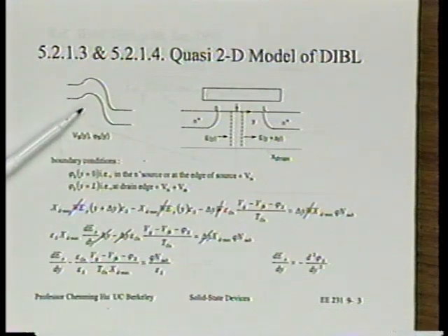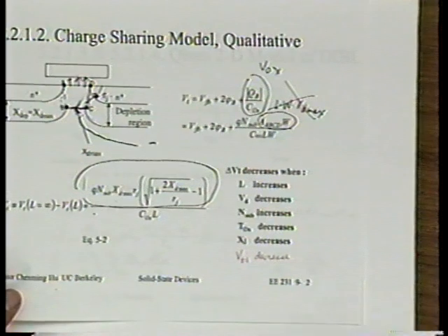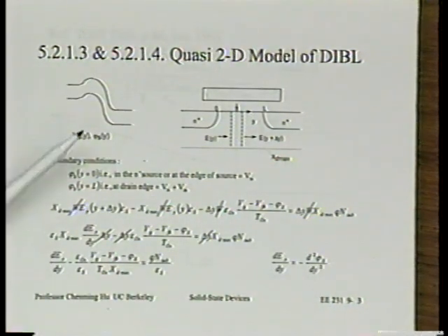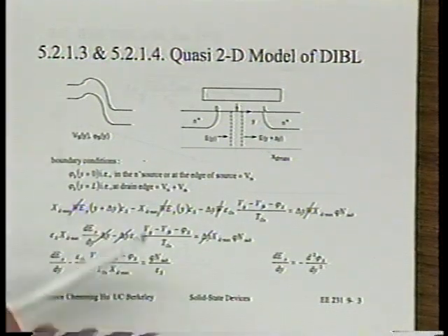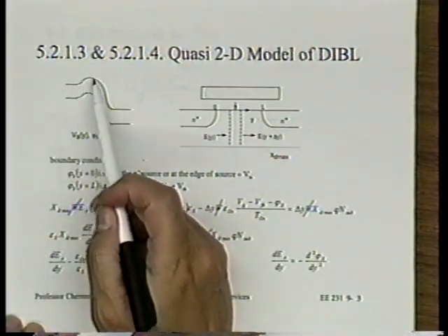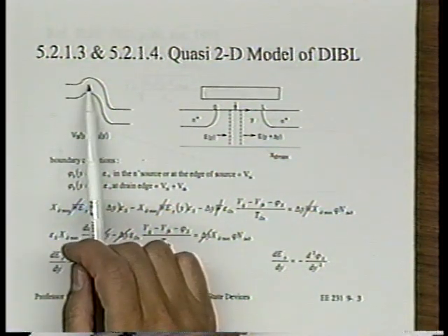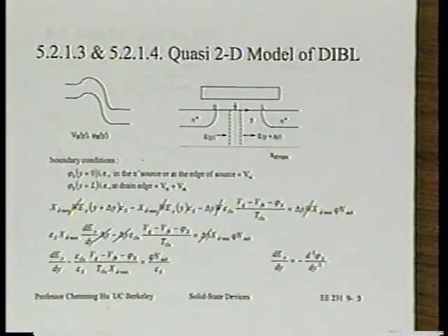So I really think that just by having this picture in mind, you can already answer the earlier list of equations. I will not do this with you, but I believe you are already able to do it. But today we're going to analyze this more quantitatively, in the sense that we're going to find an equation that describes the whole shape of this energy band diagram. If you can do that, then of course we'll be able to figure out how much this peak is lowered by Vg, by L, by Vd.